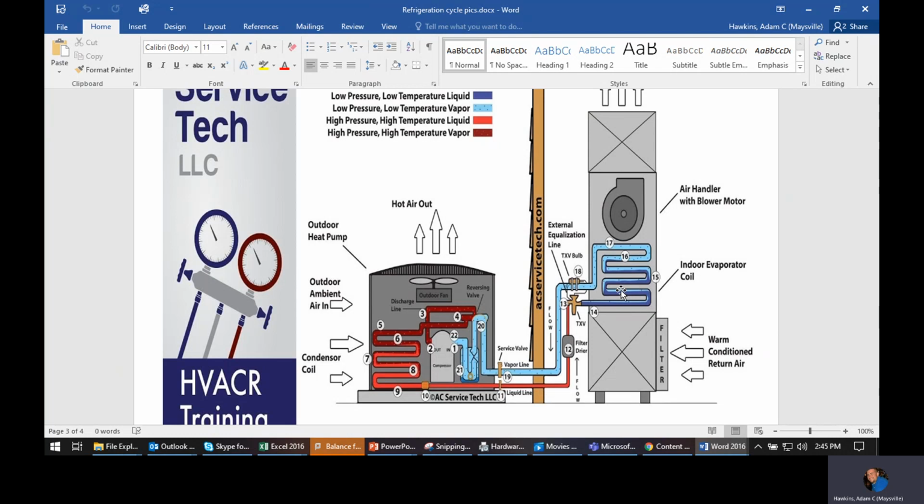So that system is designed for that house. As long as it's getting the right amount of heat, it's going to do the right amount of evaporating, and then you're going to have superheat left over. If you've got a TXV, that's going to maintain that a little bit better and make sure that it's the optimal amount. But either way, you should have enough heat available to superheat this refrigerant before you get done.